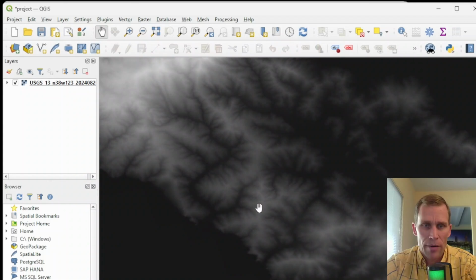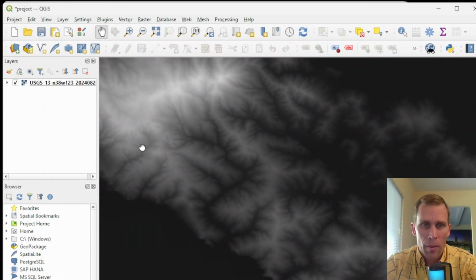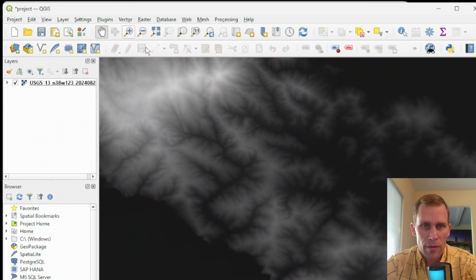Now that I know the general area of my watershed, what I'm going to do is create a polygon shapefile to use as a mask, and then only clip out the elevation data from this map to use in HMS. Therefore, I will be minimizing the processing time upon HMS GIS tools.